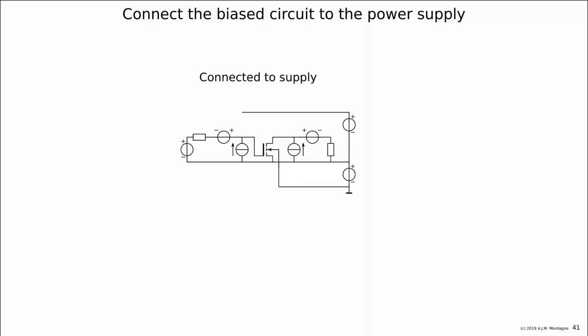And here I placed the device with some offset. Any reason for this at this moment, of course, I don't have, because I need to complete the circuit for that. But I just want to show you in general that it doesn't need to be connected to ground. You can connect it to any voltage as long as the impedance is low between the power ground and the signal ground.